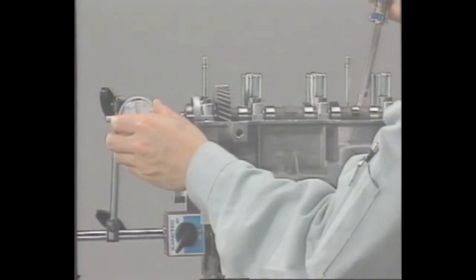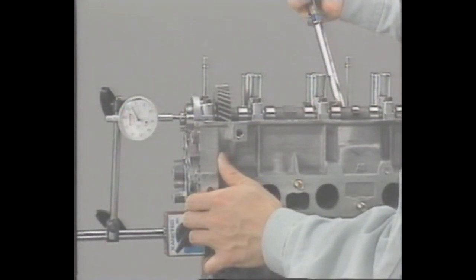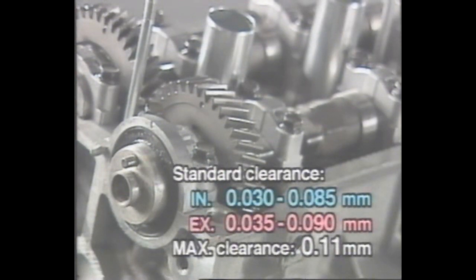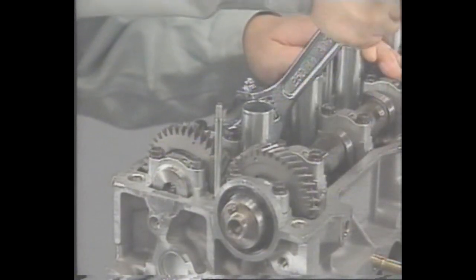To do this, attach a dial gauge vertically to the camshaft end and move a screwdriver back and forth in the clearance. The standard clearance values are shown here. If the clearance exceeds the maximum permissible value of 0.11 millimeters, replace the camshaft or the cylinder head. Remove the intake and exhaust camshafts.